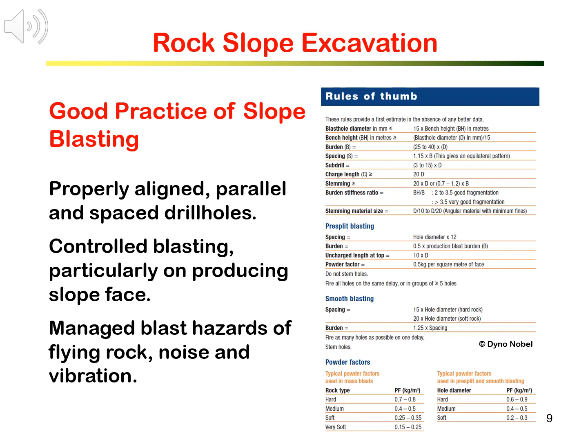Use good design and practice of explosive charge, stemming, and delay for blasting. Use controlled blasting, smooth blast, or pre-split blast to produce the slope face.